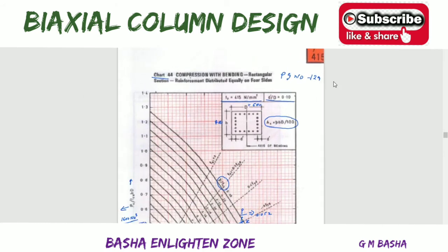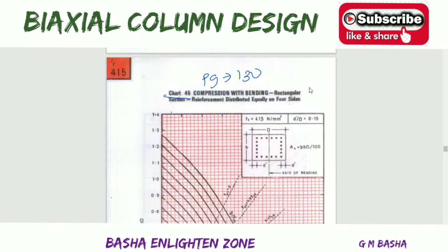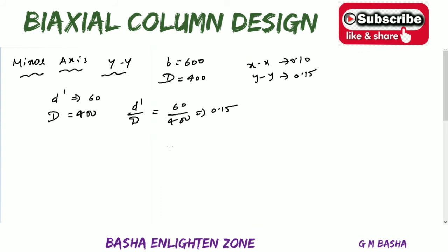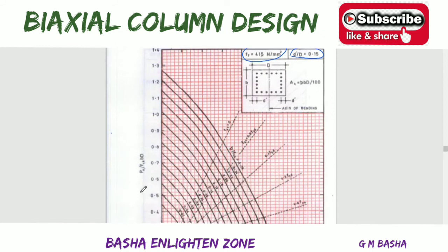Then see here, this graph is related to d dash by d equal to 0.15, fy equal to 450 Newton per mm square, and the d values will change. Therefore d dash by d ratio is 0.15, with reinforcement equally on all four sides. For this one, what we have to do is in the same sense. So what is our first point? It is better to find out Pu by fck bd. The Pu and fck bd values will be the same as the previous x axis, because we are solving the same problem.